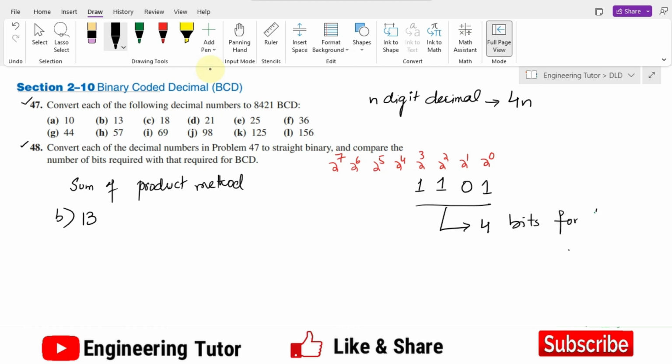for binary. And here for BCD we can see that we have 2 digits, 1 and 3. So therefore 4 multiplied by n, or 4 multiplied by 2, is 8 bits for BCD. So for BCD I need 8 bits, while for the straight binary, I need how much? I need basically 4 bits. So that is the conversion here.